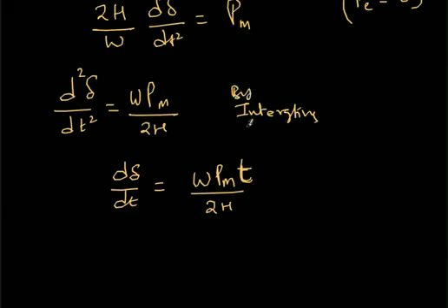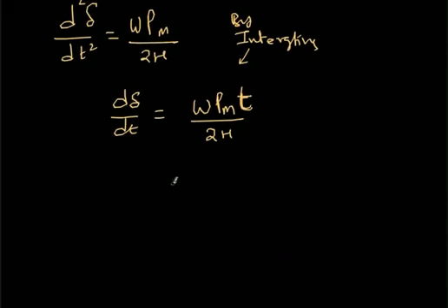By integrating, I get this. There is no constant of integration because this second derivative is actually with respect to the stationary, with respect to the rotating reference frame. So at this stage there is no constant term, or the constant term is actually 0 in this case.